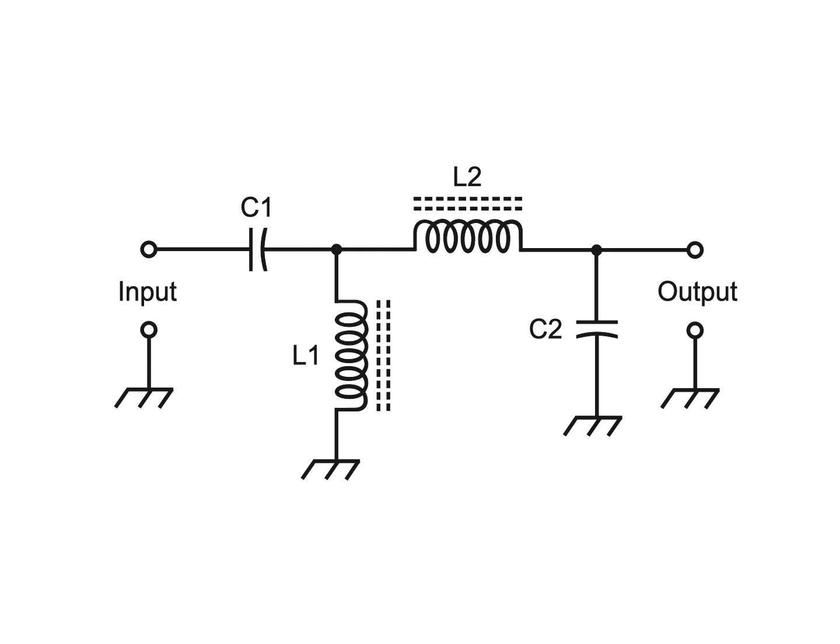Through this systematic method of elimination, all done with the help of schematics, the equipment can be repaired with a lot less trouble than you'd experience if you didn't have the schematics. The process of narrowing down a problem zone from the system to a complex circuit, then to a simple circuit, and finally to an individual component, is called troubleshooting to the component level.